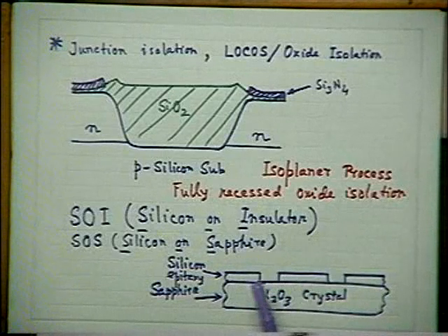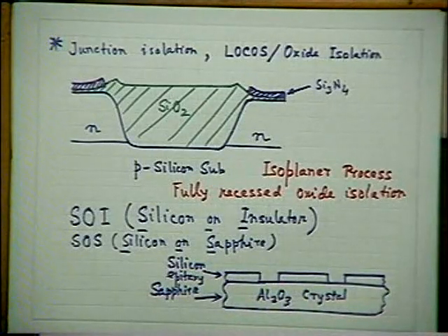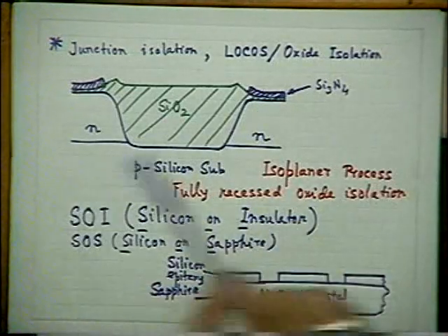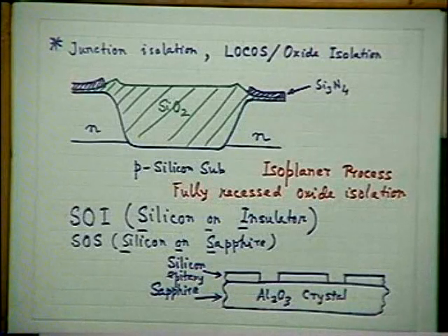And thereafter, you do the same thing as you did in normal technology. You etch windows for contacts, metallize, etc. Only thing is, the surrounding region is all filled up by a very high quality dielectric film. Everything is surrounded at the end of the process by a very high quality dielectric film. So do you know what is the end result? What is the good thing about it compared to the earlier one? Here the bottom layer component of capacitor is also eliminated to a very great extent.